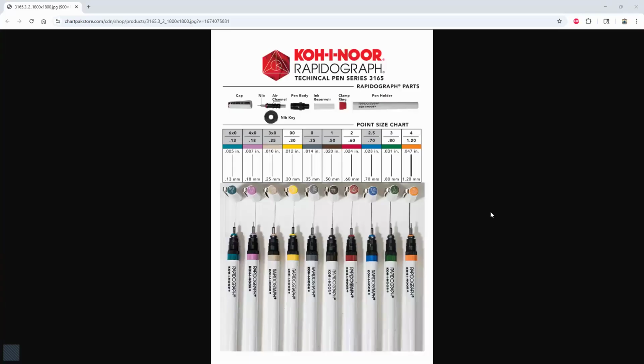All right, I just figured I'd take you down a little bit of history here. These are technical pens that we were using a lot of when we drew by hand, but I want you to see how these technical pens, they have those different line weights, and they're in millimeters here. So when I use a pen that's 0.25, I think of this line weight. And you'll notice here with these pens, they're also color coded on the caps and also on the collar of the pen. So when we were drawing by hand, we always knew that this beige color was going to be a thin pen. The yellow color, this was going to be our 0.3. That was a common one that we would use.